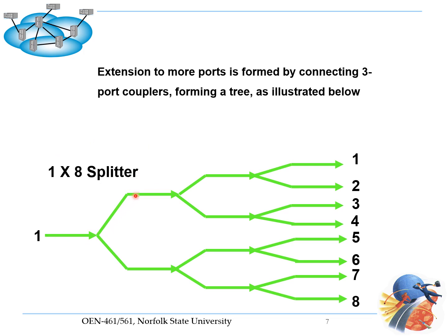So you see, we start with one Y branch, and then here is a second Y branch, and then 2 more Y branches. So in total in that system we have 1, and then 2, and then 4. So we constructed the 1/8 coupler by using 7 Y branches.